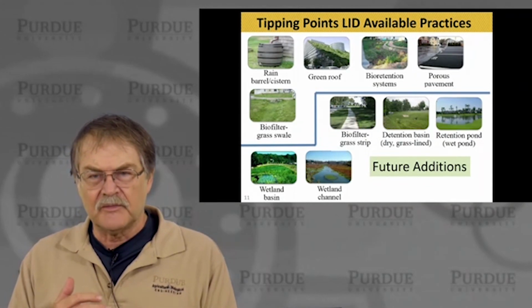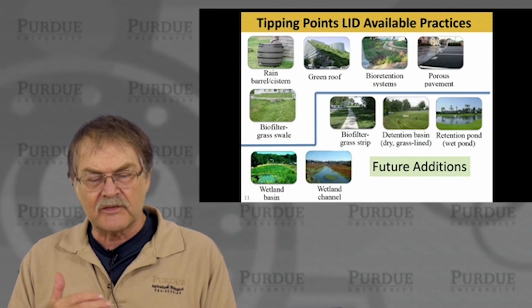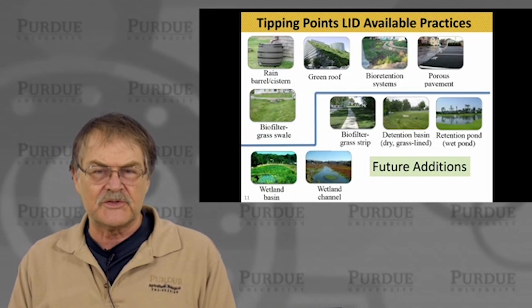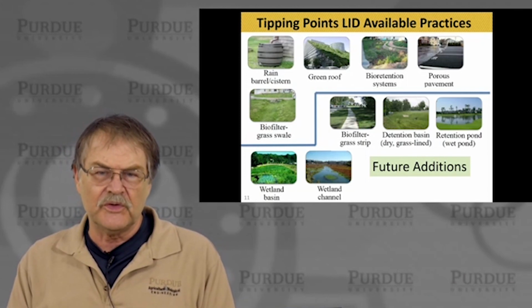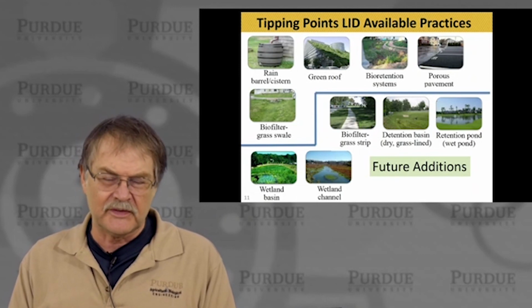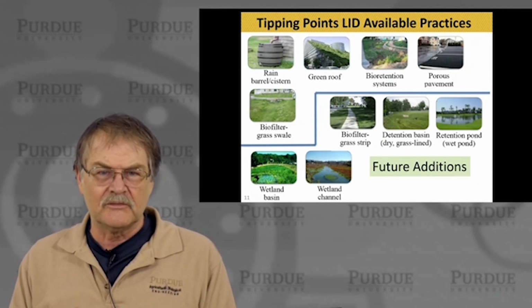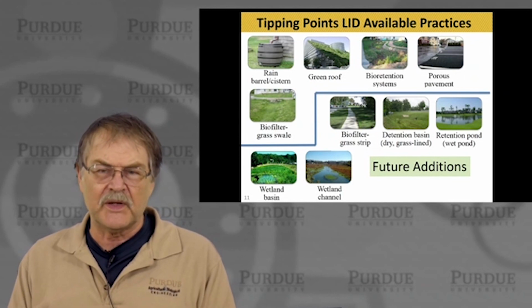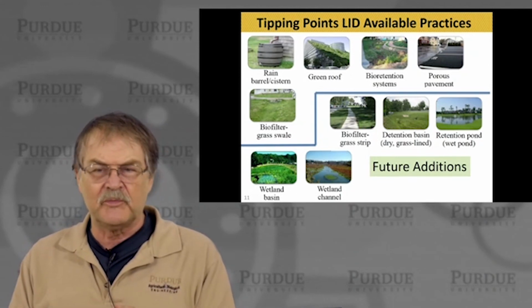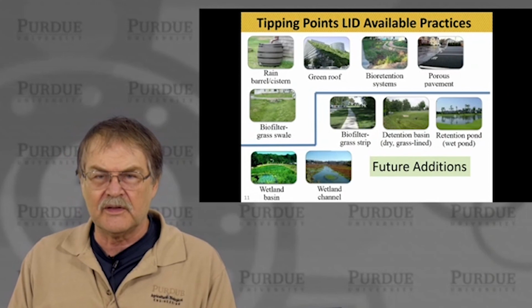So the impact of these is computed as if they are spread through all the houses in the area you've drawn. So you don't dot a house and say, I've got 1 rain barrel, what's that going to get me? Because really that won't get you anything. But you can draw a box on 500 acres and say, we're going to change the zoning, the new place is going to have porous pavement, and what's the impact? And the computer then says, okay, 500 acres, 2 acre lots is going to have certain square footage of pavement, we'll make all that porous, what's the benefit? And that'll be the answer.